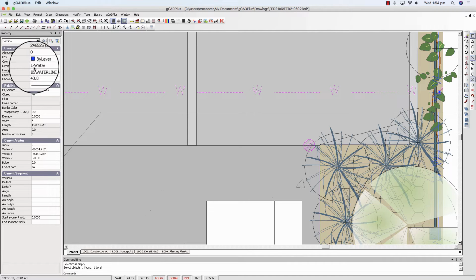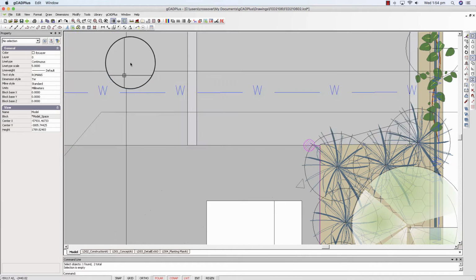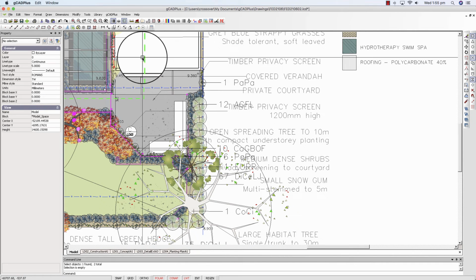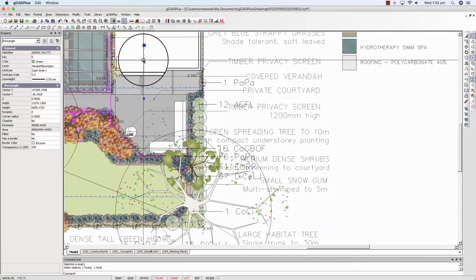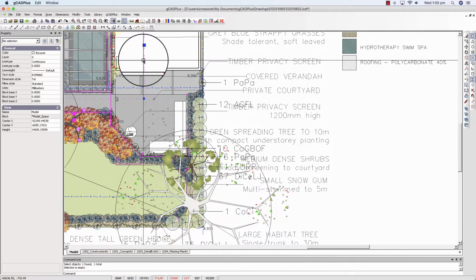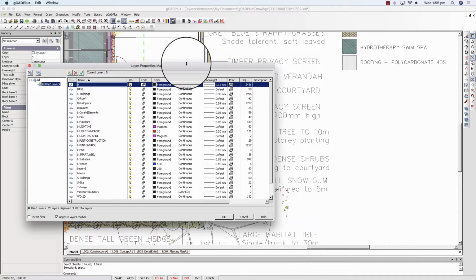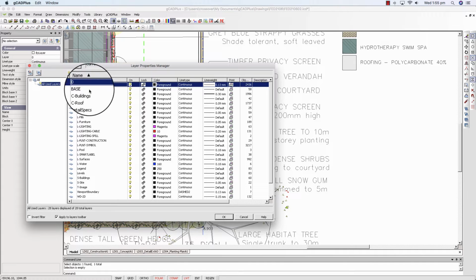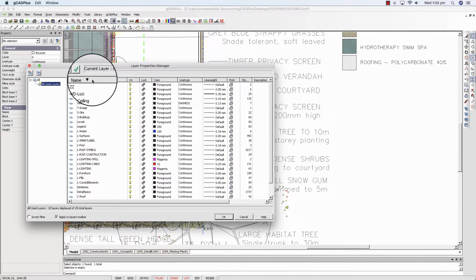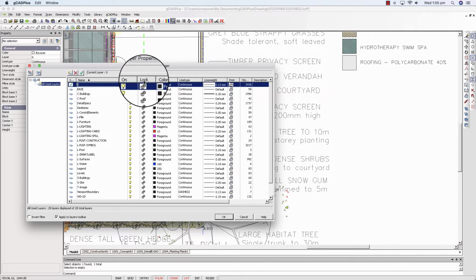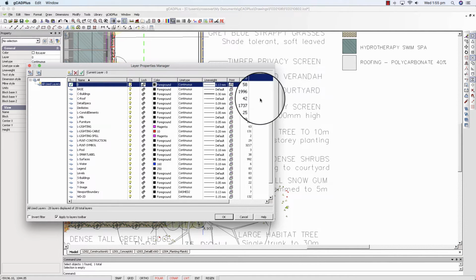We're in the habit of, if we're going to create a new layer, calling it L-, and the reason for that is if we just zoom out a little, this one here is on a separate layer called viewport boundary. But if we go to the layers dialog box, it's really quite powerful and you can do a lot with this box. You could click at the top of columns and change, now it's in reverse order. You can play with locking whole groups of layers and so on.